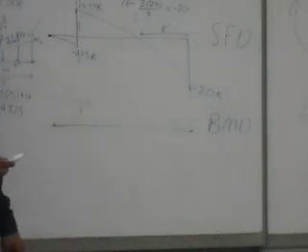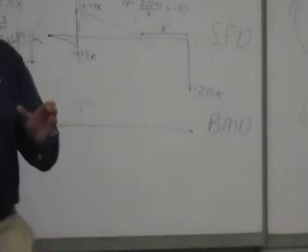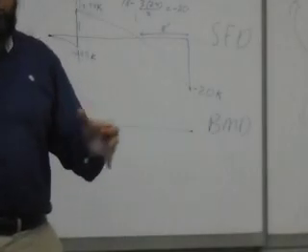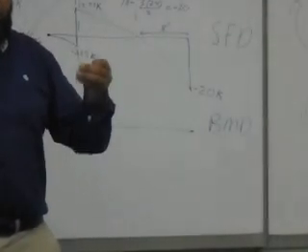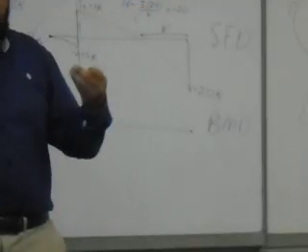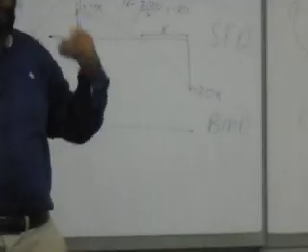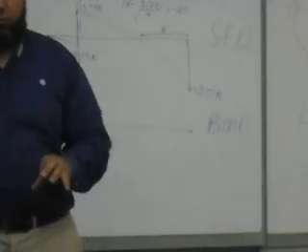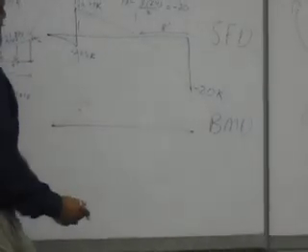Do you understand the idea? So you ladies, you need to understand this. You're not integrating or differentiating anything here, but you need to understand the relationship. You need to understand that there's an integration relationship between the bending moment and the shear force, in order to understand whether you are doing something right or wrong here. Okay?